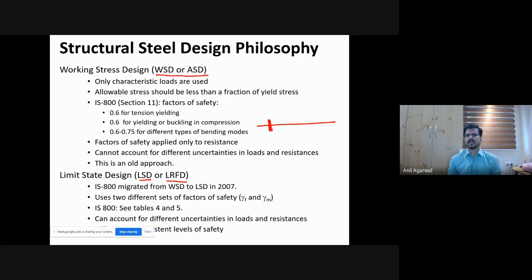So you would calculate the live load, dead load, wind load, based on the respective codes which provide you the load values. And this is the Q value. And R, of course, it was understood that there was a distribution.